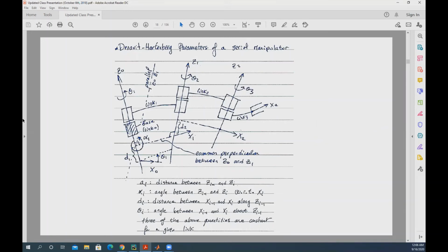Sometimes the end effector on the robot will give you the position of an object, and it will give it to you in frame 6. Let's say you have a camera connected on your end effector, you will be able to use H06 to find the coordinate of that point in your base frame, and vice versa. Sometimes you can have a camera in your world frame, and you want to convert what that camera is seeing into the end effector frame, so you'll know how to move along the end effector frame. If you map an object and it turns out to be along X6, all you need to do is move along X6, and then you will approach it.